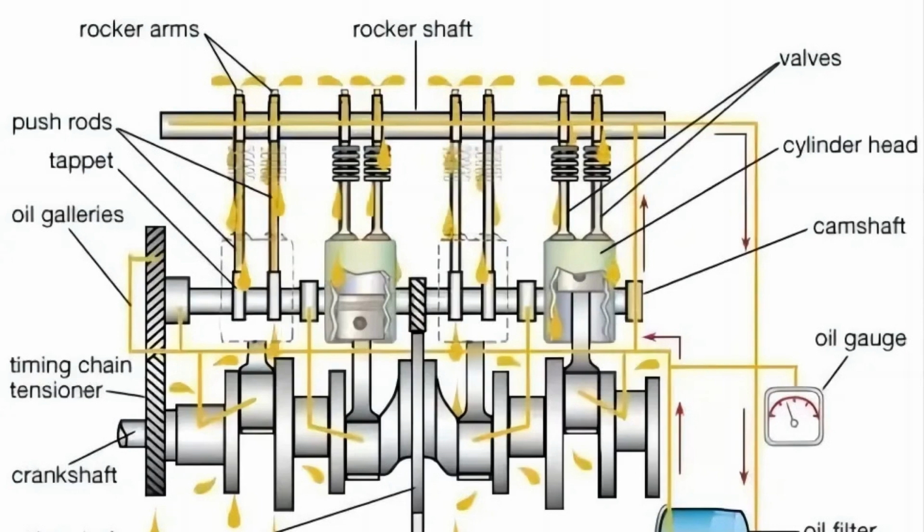During prolonged parking, oil under the influence of gravity flows down the line into the crankcase sump, and most of the engine parts remain without lubrication or with a minimal amount of it. By starting the engine, you provoke oil starvation, which, although short-term, manages to cause minor damage. Thus, non-compliance with the starting mode only aggravates the situation. In this case, the accumulating effect is much stronger, reducing the overall life of the power unit.